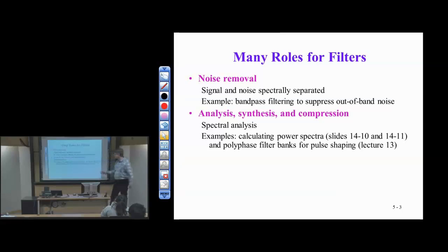Also, what's interesting in compression is that both our auditory system and our visual system are roughly low pass. In the case of audio, it's low pass in frequency, and again, we hear out to about 20 kilohertz. For visual, it's low pass in both spatial frequencies and temporal frequencies. Frames would be time in a video sequence, and each frame would be a snapshot of space.